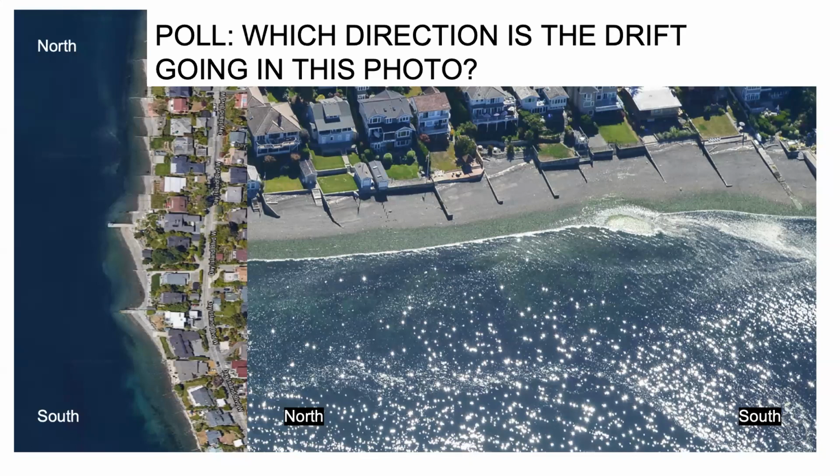And then on the oblique there, you can actually see some of the shadows where there's no material on the downdrift side of the groins, and there's no shadows on the updrift side of the groin where material has essentially filled up that little vertical obstruction.